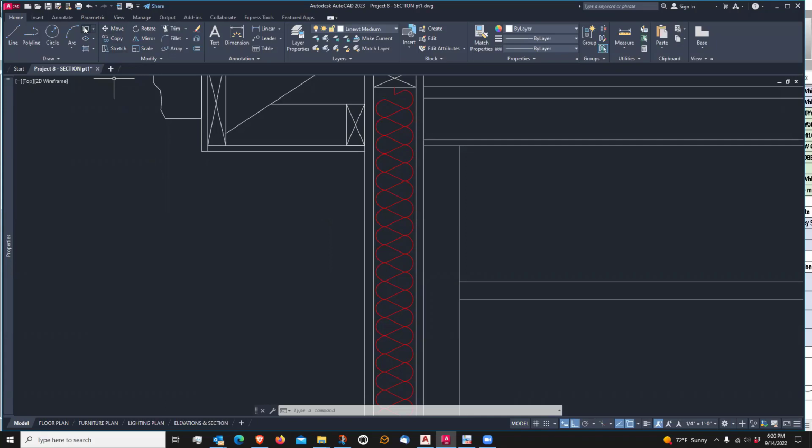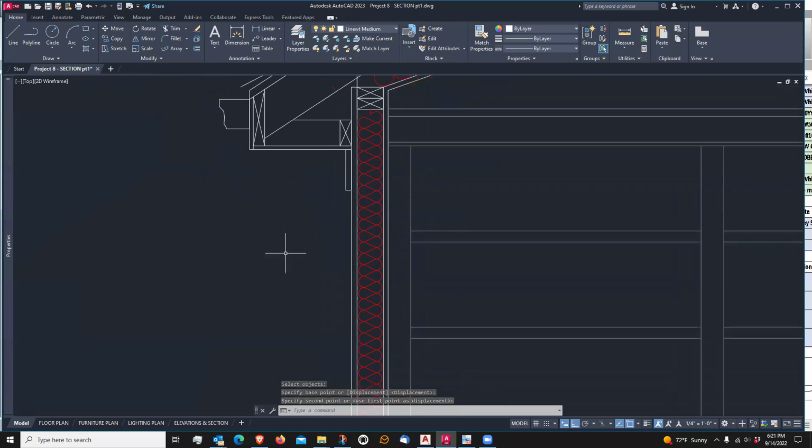So I'm just going to use my trusty rectangle tool here, and draw a rectangle. Again, it's 3/4 of an inch, so I could do 0.75 or 3/4 if I want, and then hit my tab key to get the vertical dimension, and that is 5.5 inches. So there's our trim piece, and I am just going to grab it and move it right into that corner. All right, good.